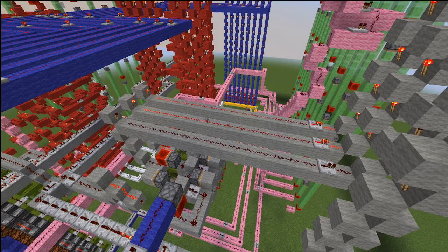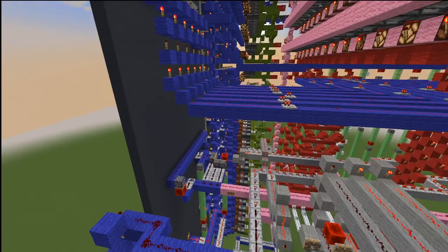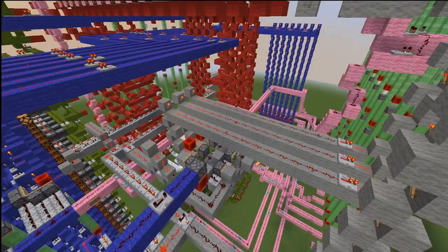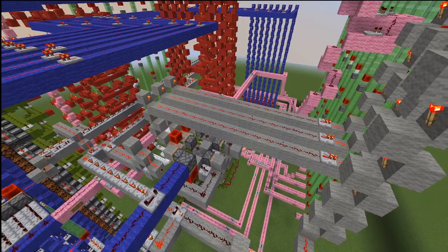The next macro instruction that's going to run is load the accumulator, and as I explained earlier, we're going to load the accumulator with what's stored on PROM line 5. And all that's going to do is take that data from 5 and send it to the A register. And you'll see how the computer does this.